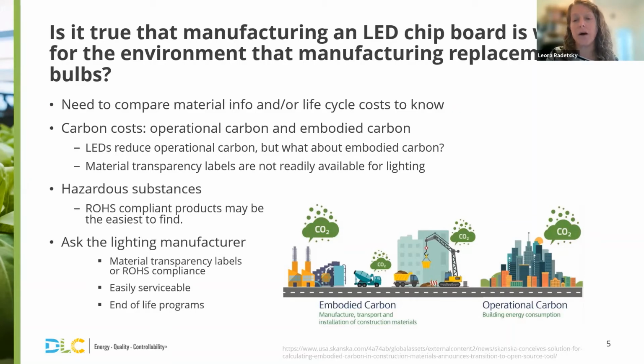And so on the hazardous substances end, you can start to look for RoHS compliant products. RoHS stands for Restriction of Certain Hazardous Substances. It is a European Union directive. It's on its third revision now, RoHS 3 is the one now. Essentially, what this does is it restricts the inclusion of materials for electric and electronic devices like lead, mercury, cadmium, and there's a bunch of others, in order to make them more environmentally friendly.